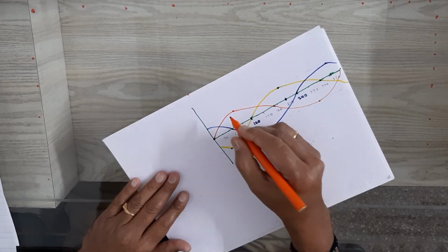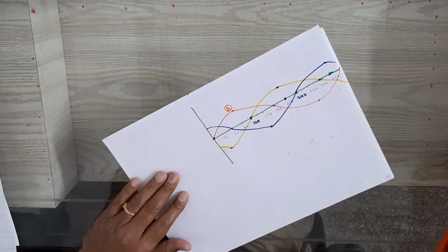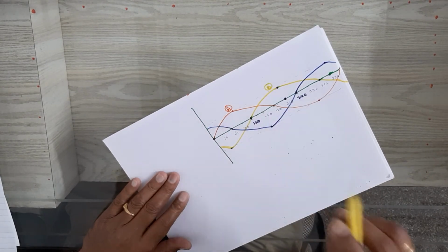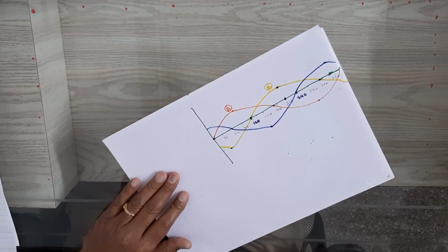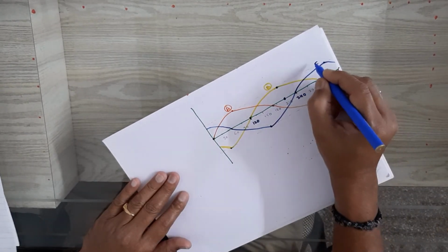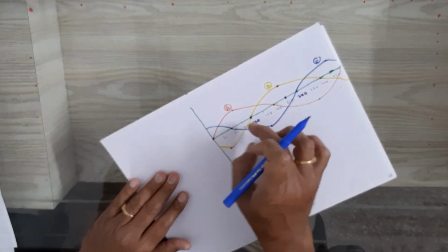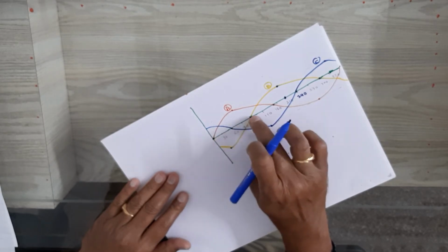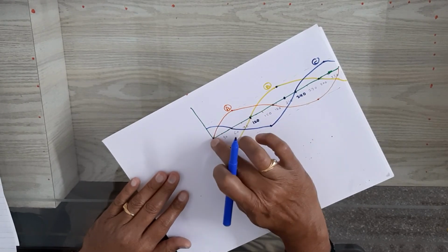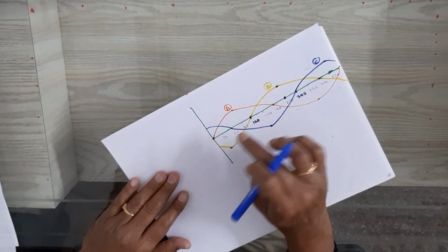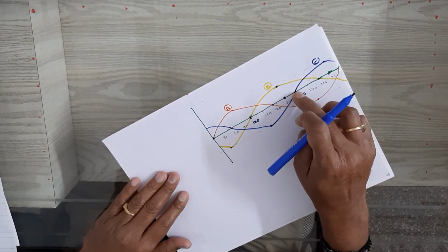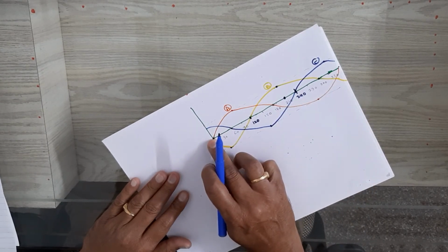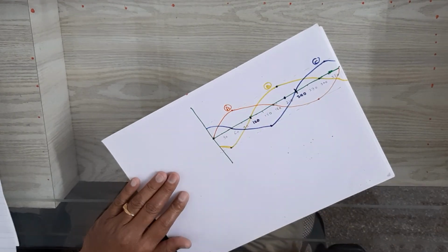This is the waveform for A coil, waveform for B coil, and this is the waveform for coil number C. You can see here clearly the second coil starts generating the voltage 120 lagging A. Its 0 value is lagging by 120 with respect to A, and if you are comparing C, it is lagging by an angle of 240 with respect to A, or 120 with respect to B.